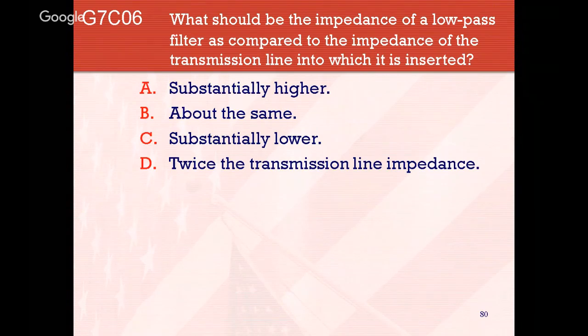You could put a high pass filter on the back of the TV so that only those frequencies that the TV is designed to receive will pass through that high pass filter to the TV, namely the TV station transmissions, and block anything that is of lower frequency, namely your HF transmissions.